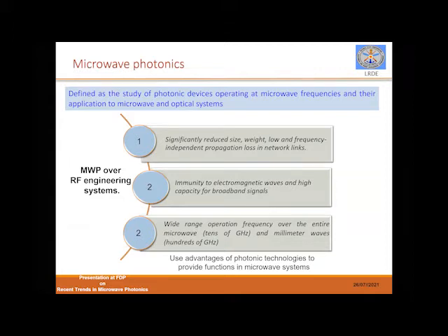But in the case of the RF domain, if we are going with a mixer stage, it is frequency dependent. I cannot convert directly from an L band or baseband signal to an RF frequency of higher order. It is very difficult. You may have to have two levels of up conversions. Do you agree with me?